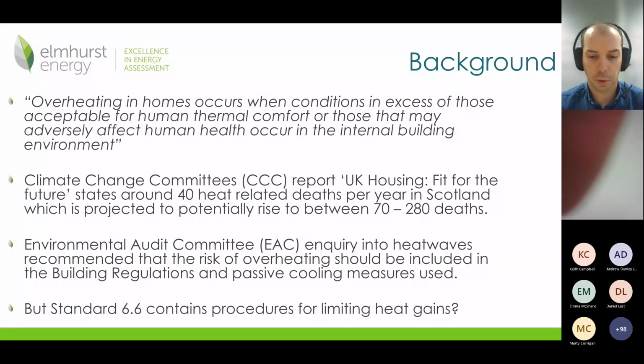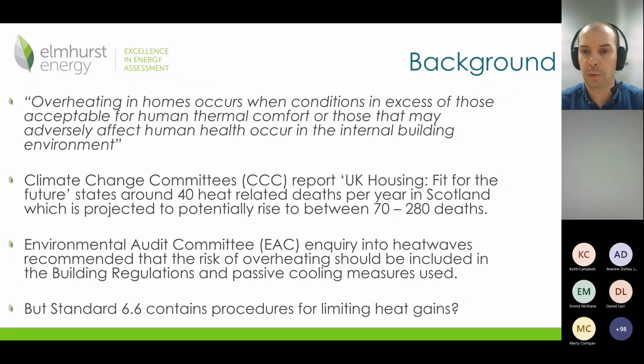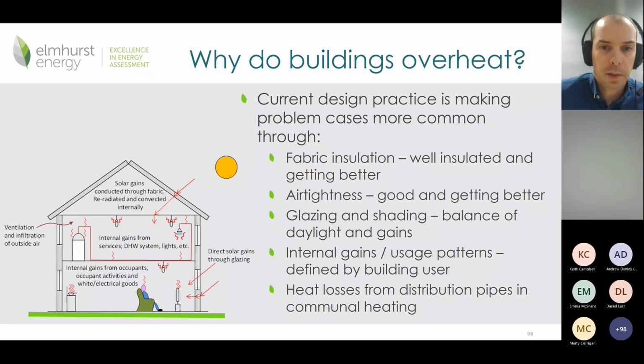But obviously, again, we've had a push towards more well insulated, more airtight homes, which is great for energy efficiency, but not also great for overheating. Okay, so it started to become an issue that the government were concerned with across all areas of the UK, not just Scotland. Okay. Why do we overheat? As I said, we're pushing for more and more insulation. We're pushing for better and better air tightness, glazing and shading. You know, developers, architects like their big windows. Not so good necessary for overheating.